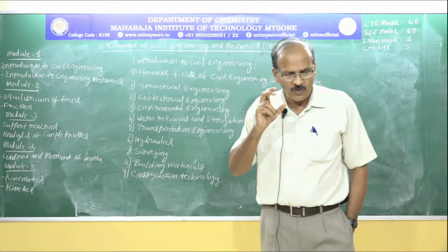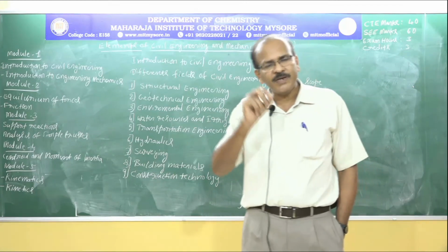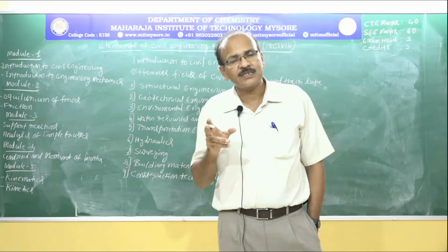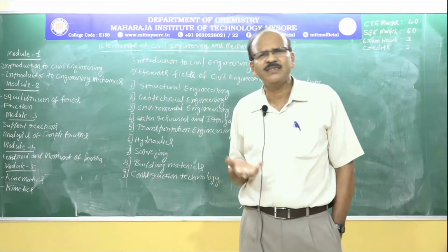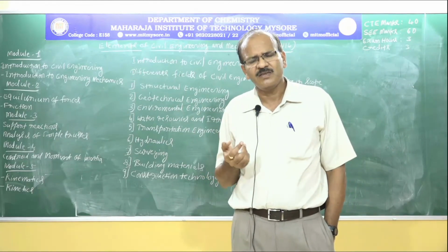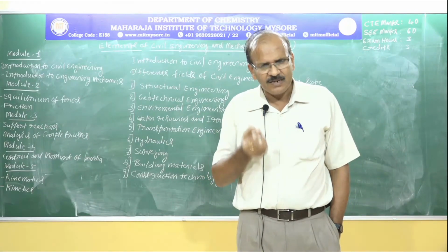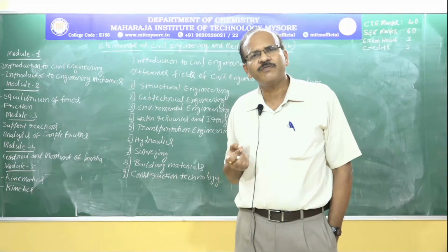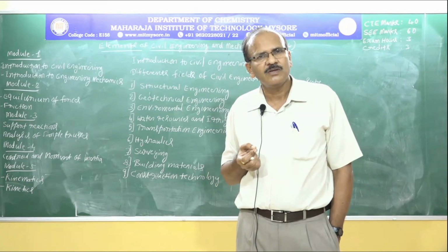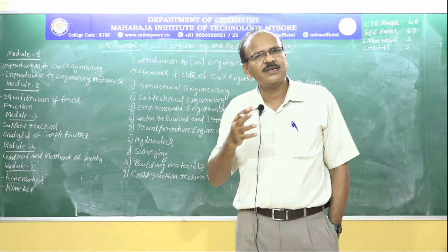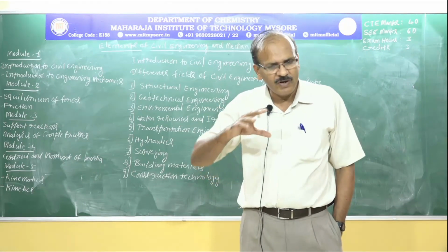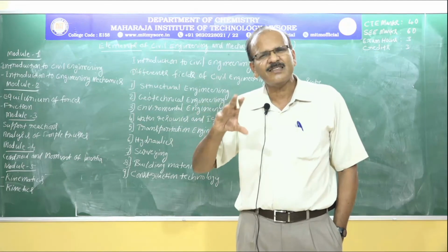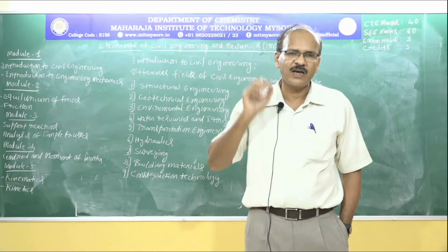Once we get that material, before using that particular steel, because it is manufactured by different manufacturers, when we test it, the strength should be at least 450 Newton per millimeter square. It is not as simple as I am saying now.